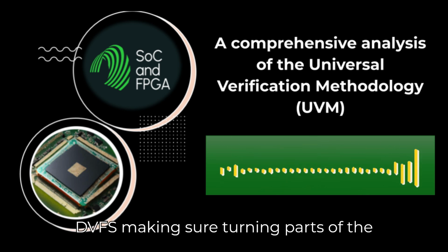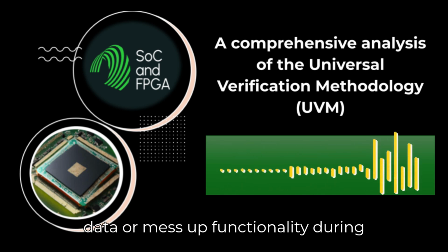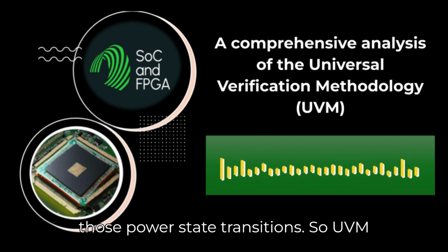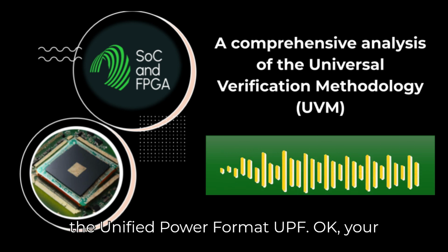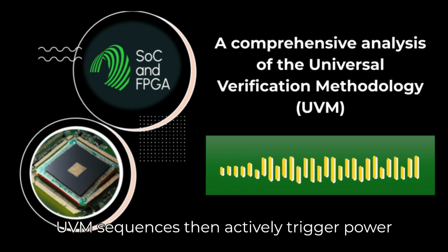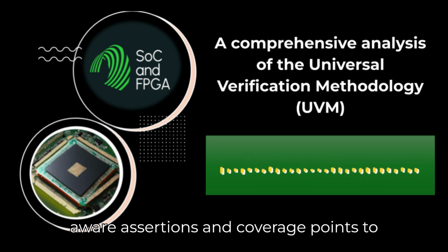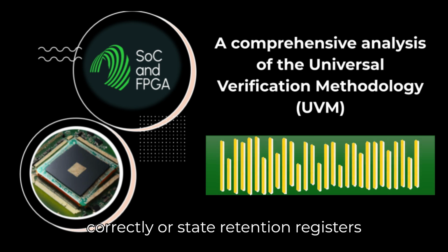Making sure turning parts of the chip off and on doesn't break things. Exactly. Making sure you don't corrupt data or mess up functionality during those power state transitions. So, UVM test benches get integrated with a power intent specification, usually written in the Unified Power Format, UPF. Okay. Your UVM sequences then actively trigger power state changes, and you use special power-aware assertions and coverage points to check things like isolation logic working correctly or state retention registers holding their values.